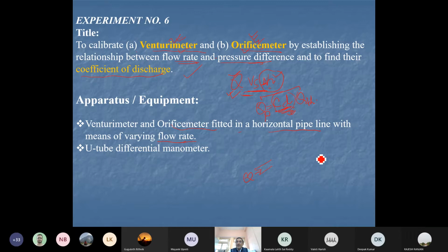So it's a U-tube manometer you have already learned in your fluid mechanics classes, but simply here I will try to recollect that learning. So a U-tube manometer, if it is fitted in a pipeline system, simply here suppose it's a pipeline, it measures the pressure at the center of the flow line by using a U-tube that is connected to this.